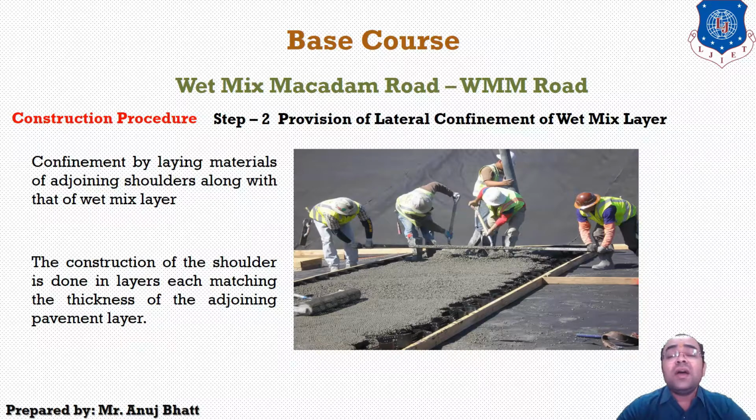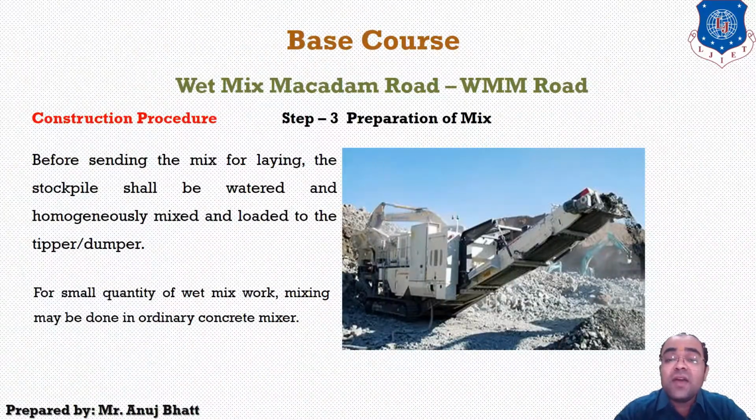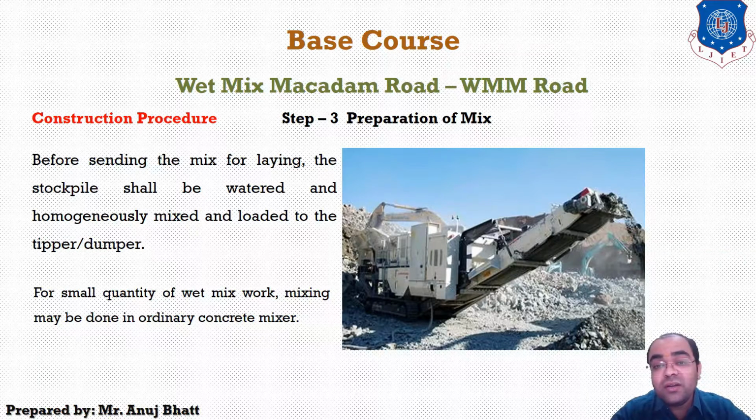Now, after providing the confinement, we have to prepare the mix. So step 3 is the preparation of mix. To prepare the mix, the material should be stockpiled with the front end loader. Before sending the mix for laying, the stockpile shall be watered, homogeneously mixed and loaded to the dumper.